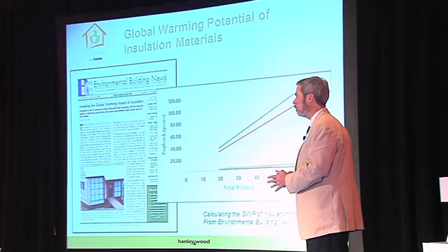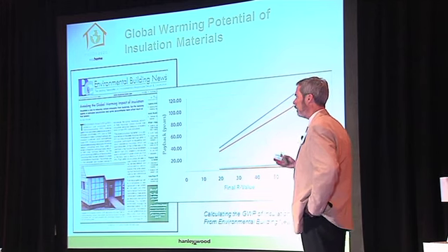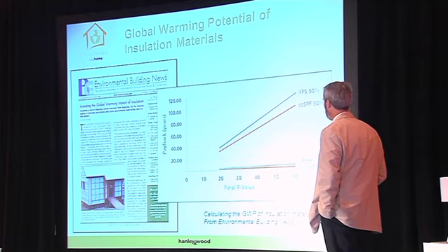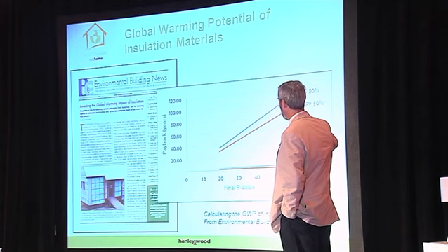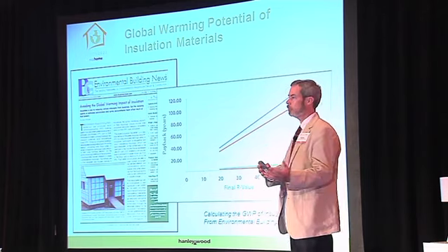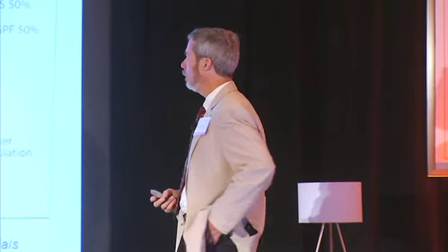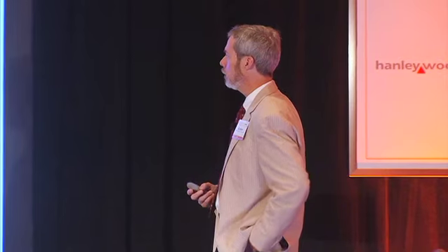In most cases, it's always good, if you're at R20, to go to R30, if you're at R30, to go to R40. But what we showed with this study, and it was based on some scientific research that had been done, is the payback through energy savings. When we save energy, we reduce fossil fuel consumption, which reduces carbon emissions. There's a significant payback issue that can, in some cases, span 100 years or even longer to pay back that embodied global warming potential that's going to escape over time, over the life of those insulation materials.